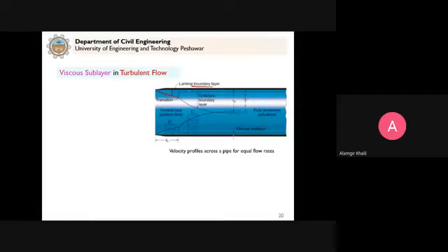As we already discussed, first we will have the laminar boundary layer, and then there will be a transition to a turbulent boundary layer. Because of symmetry, it will happen from both sides, as you can see here. Those turbulent boundary layers will meet and occupy the full pipe. As a result, we have a fully developed turbulent flow.